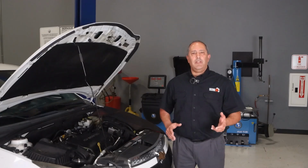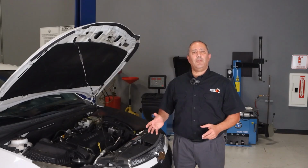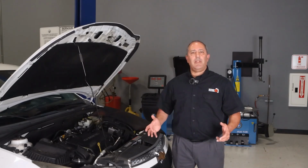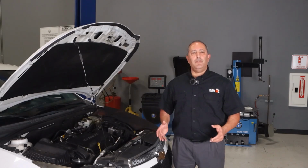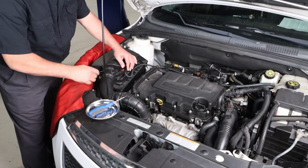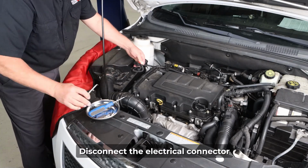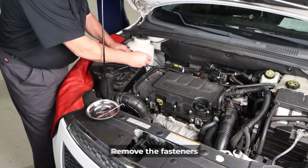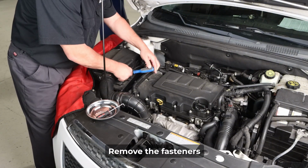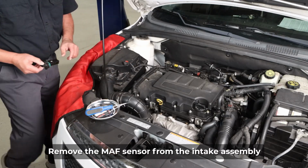After completing the diagnostic steps, we've confirmed that the mass airflow sensor is the cause of the issue. Follow these step-by-step instructions to replace the sensor. The mass airflow sensor is located in the air intake system near the air cleaner assembly. Begin by disconnecting the electrical connector, removing the fasteners, and carefully removing the MAF sensor from the intake assembly.